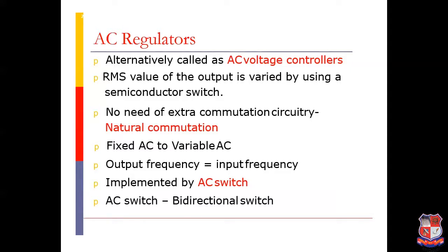For example, we want to control the speed of AC motor using transformer, and the required variation in speed is 1400 rpm, 1410 rpm, 1412 rpm, 1413 rpm, etc. Such a precise and smooth control cannot be achieved using transformers. Also, as the rating of transformer system increases, the size of transformer also increases. And as the rating of transformer increases, the copper losses in transformer also increase.